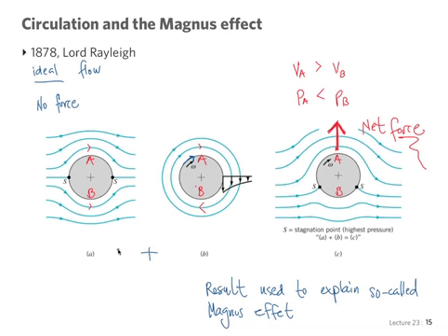In the real case, it would be the object, but in this case, it's an ideal flow where we're just thinking that the external fluid somehow has a rotation, and since it's inviscid, we don't impose the no-slip boundary condition, so the circulatory motion is present in the fluid without the effect of the solid in the ideal case.